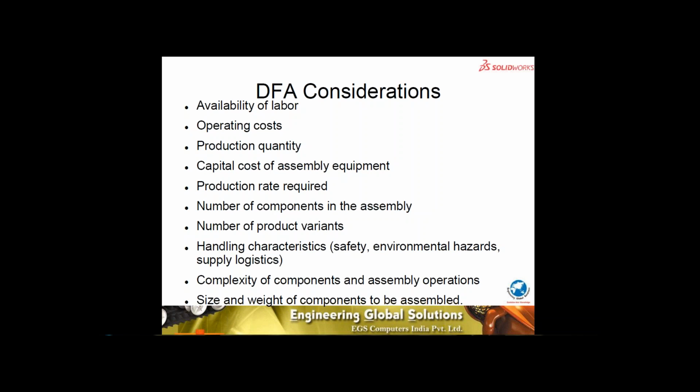The packing list contains 2 fewer components, and then your assembly time, the fastening time, and everything else comes down. So the number of components in the assembly, if components are integrated together, then we have integrated designs which help us to reduce costs.